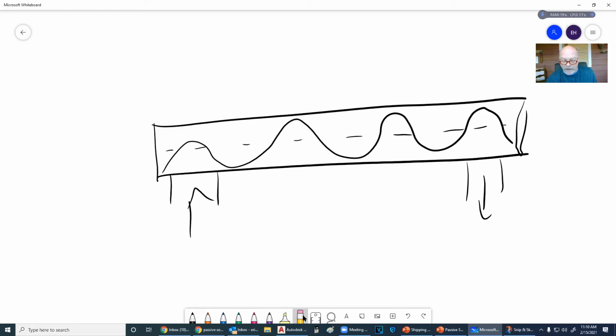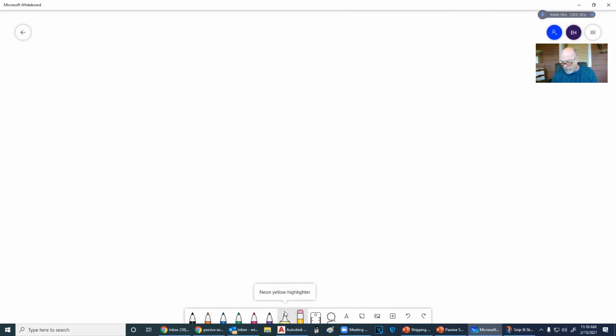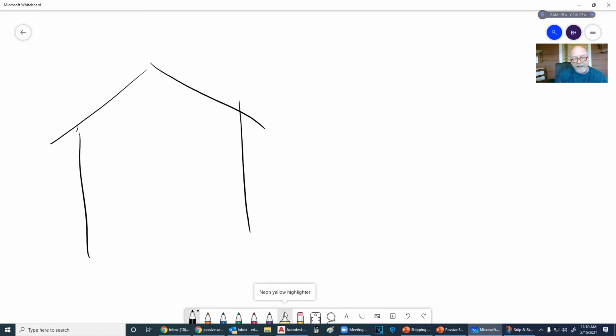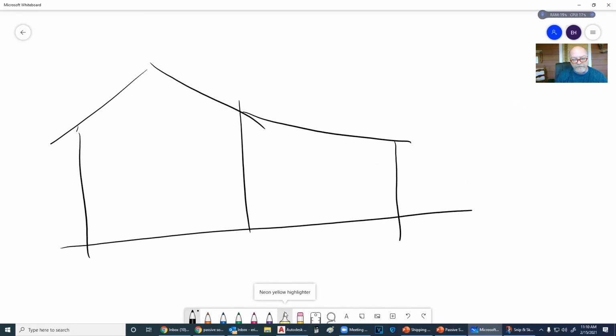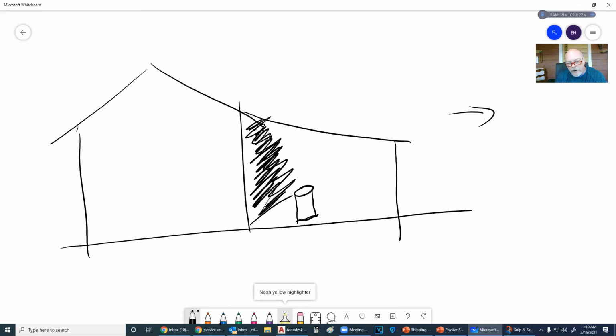So in my solar technology class, we talked almost 100% on passive solar and so forth. I had a student at Western Piedmont, at another school, and they had a greenhouse, and she wanted to try to get this greenhouse effectively able to sustain life in the wintertime. So she went in here and she painted this wall completely and totally black. Now this thing faced south, this is solar south. Then she put in a whole row of 55-gallon drums and put water in them.